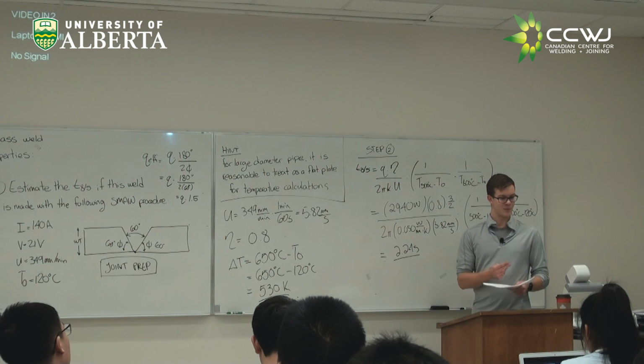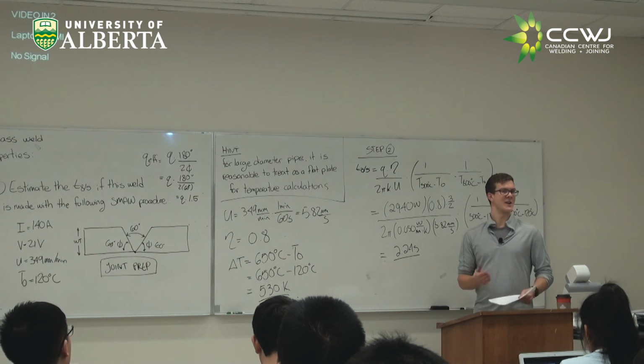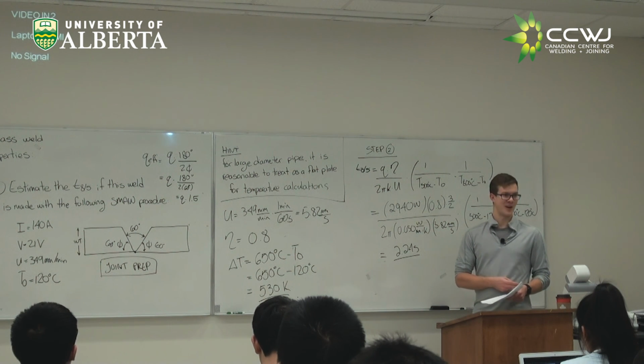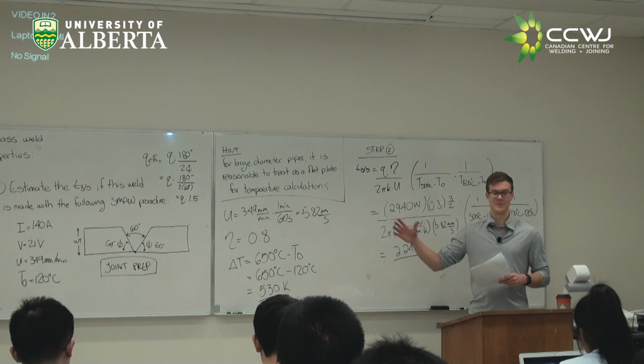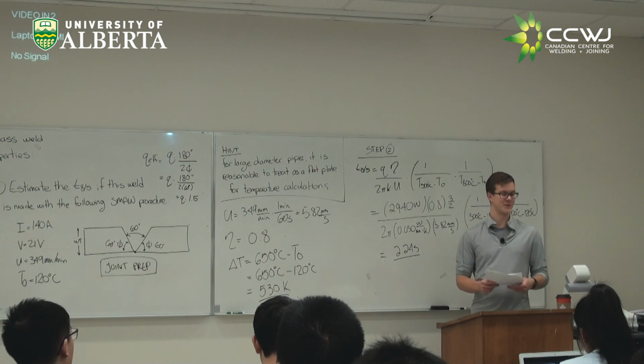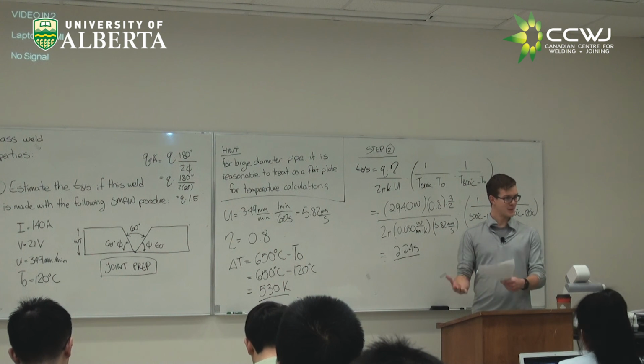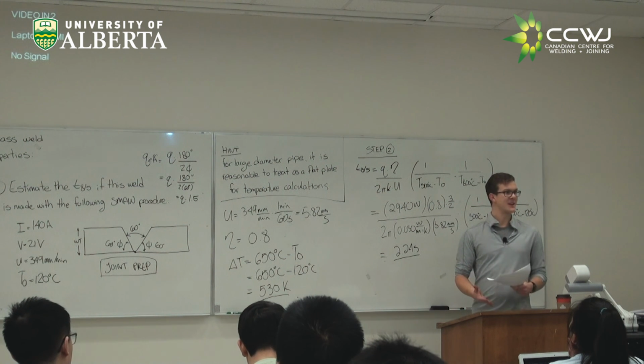You could figure out for your given steel what kind of hardness you might want, for that hardness what kind of heat input you might want, and for that heat input what kind of parameters you might want. And get all the way from something you could pick up anywhere, what you want to weld, and come up with maybe not a perfect procedure, but certainly a good starting point for how you want to weld it.